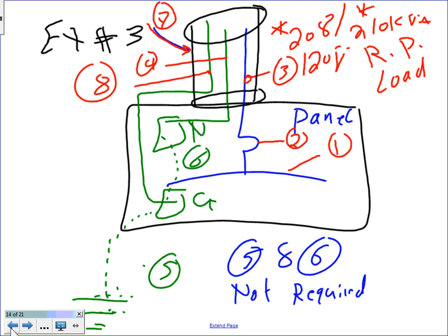If I have a transformer that's going to be feeding a panel, what I end up doing is matching the full load amps of the transformer to the full load amps of the panel, and they're mismatched. So that mismatch is the only thing I want to do. I can give you my 2 cents on how to do the mismatch. Because you find a transformer that gets you 83 amps, and there is no 83 amp panel. So I want to go to a 100 amp panel and size everything for 100 amp. So it's not really rocket science.